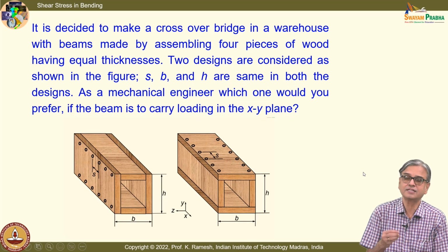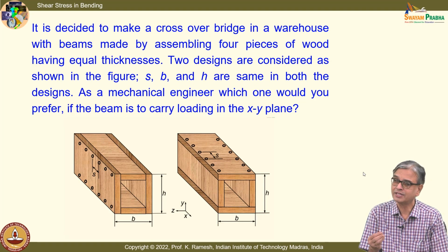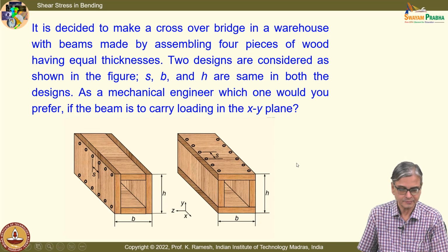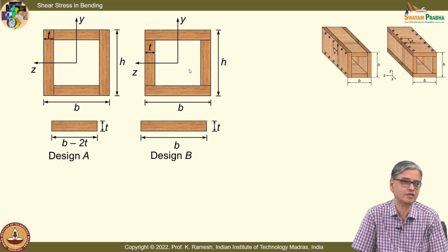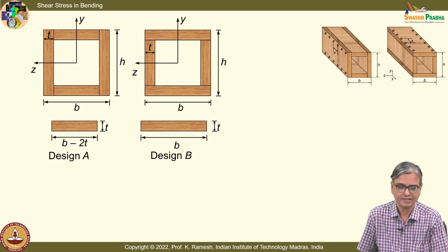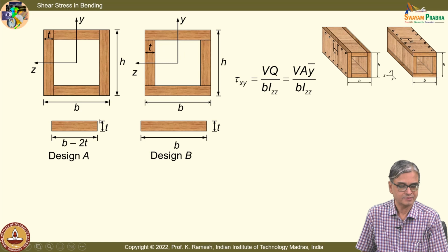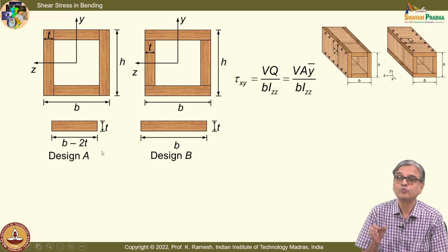See, this is just to give you some food for thought to realize how the imbalance because of the variation of bending moment is going to cause the shear stress, from an academic point of view. Is the idea clear? I have two cross sections like this. We have already discussed the expression for shear stress. We know that this is nothing but VQ by Ib, and then you know Q is nothing but the first moment of area of the cross section. So, what happens in this situation and what happens in this situation? Because I am nailing it horizontally here, this is the one which would try to have a relative motion which needs to be arrested by the nails.